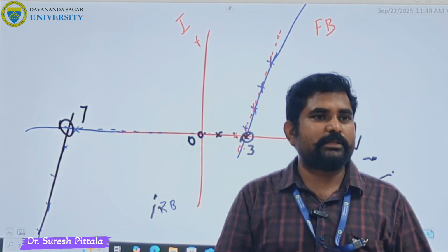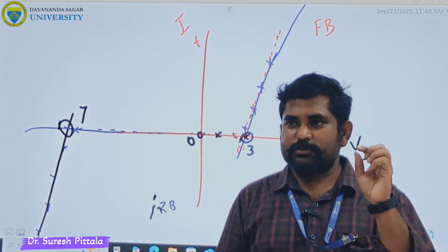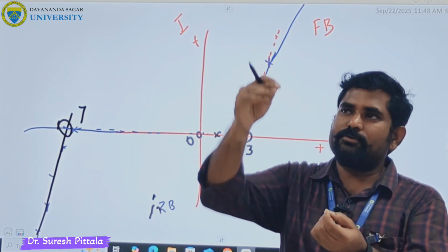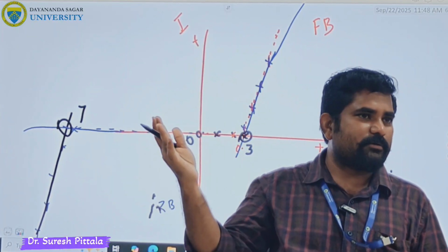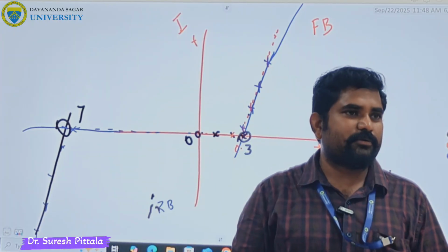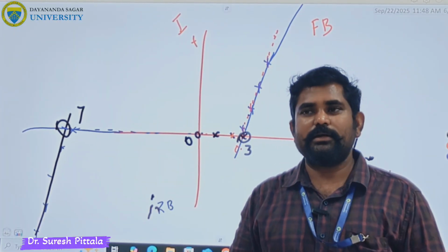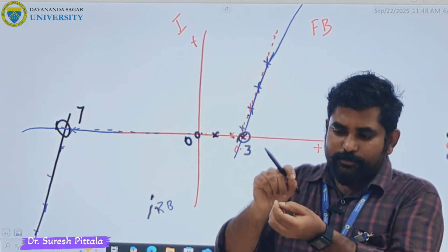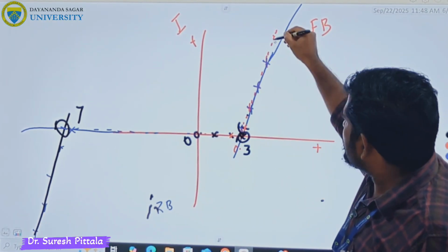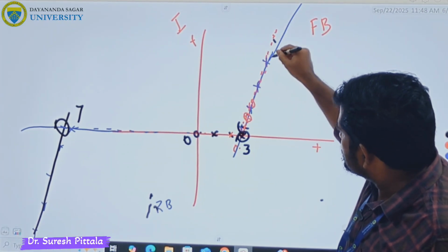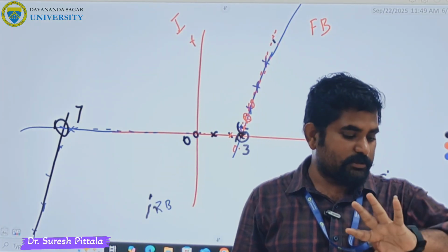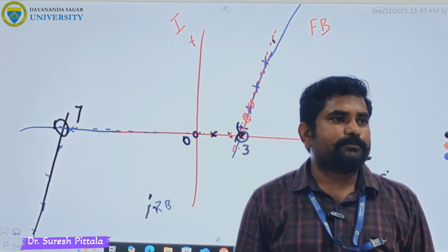But in the table, while taking the readings, take as many points as possible. Understand? For 20, don't start with 1 ampere, then go to 10, go to 20, over. Only 3 points you have. Not like that. If you can manage to take 10 readings between 1 and 20, hats off. 20, even greater. Take as many readings as possible. Look at the current and maintain the gap between these points as small as possible. For that, you have to increase the voltage smoothly, as smooth as possible. Understand? Okay. So this is the Zener diode experiment.